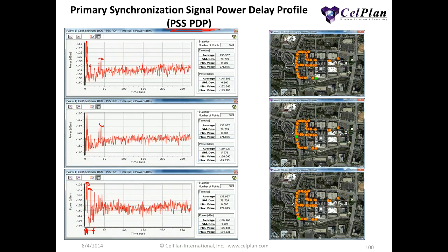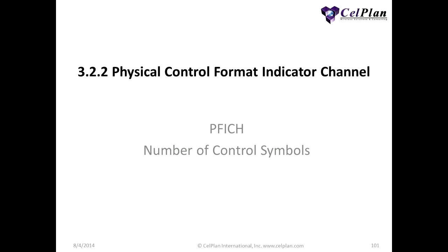So it's very important to be able to measure. Here are our drive test measurement results, a two-dimensional measurement. We can analyze them for the whole area of the cell and get different values, this one for this point, this one for this point. You can see how it varies with where you are in the cell, and based on this we select the cyclic prefix that we can use.